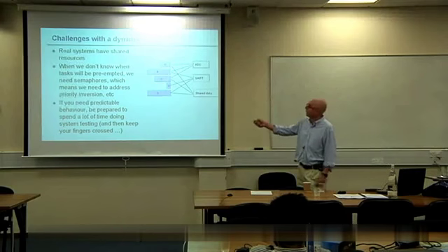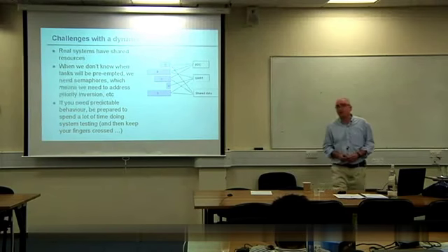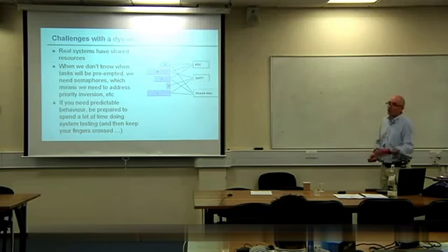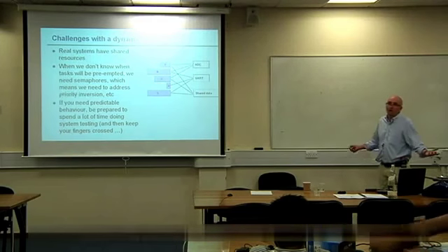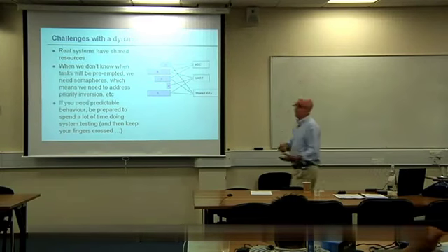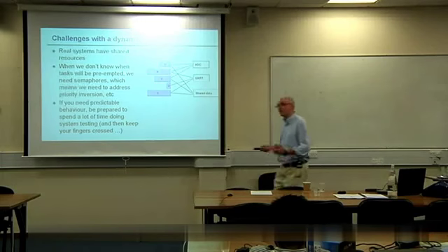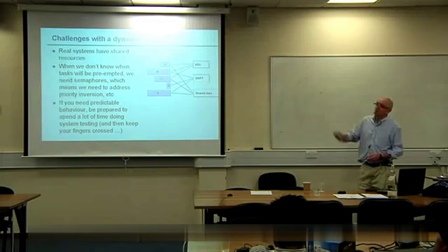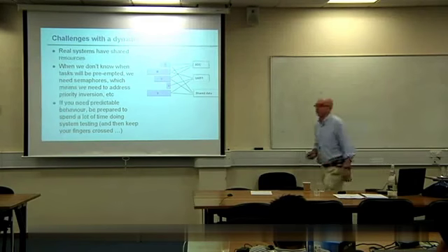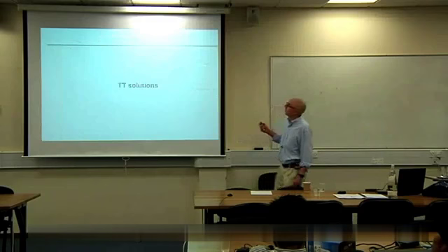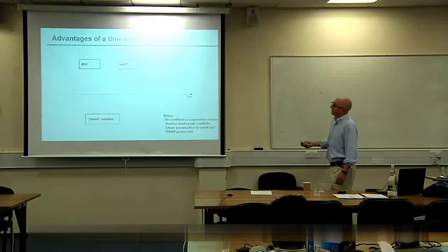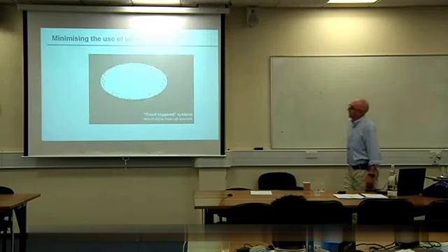Many systems run at 90% plus loading. They just don't have spare capacity for error. It's back down to the cost issue again. If it was running at 20%, they'd have used a smaller processor. So they tend to get them back up and running at about 90%, because that looks like a cost-effective solution. You've got very little headroom to deal with any errors in these circumstances. So that's one of the differences between some of these designs.